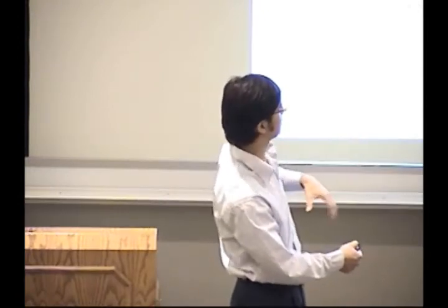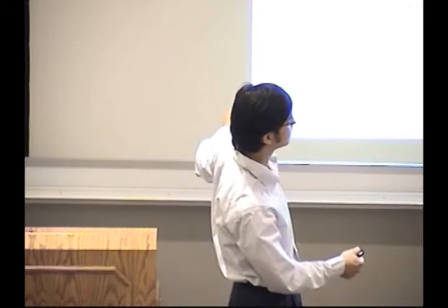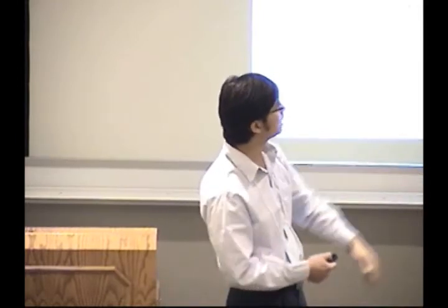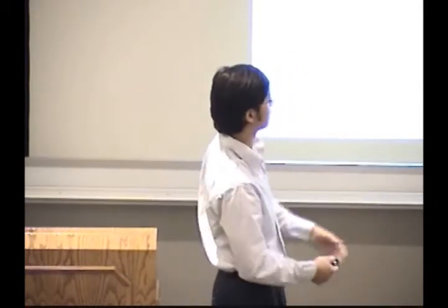The left is the downstream end. And from this slit out here, you have a pneumatic jet that continuously blows out tangential to the wall. And then this triangular structure out here is a micro ramp, which creates the vorticity that you require to again have flow control.